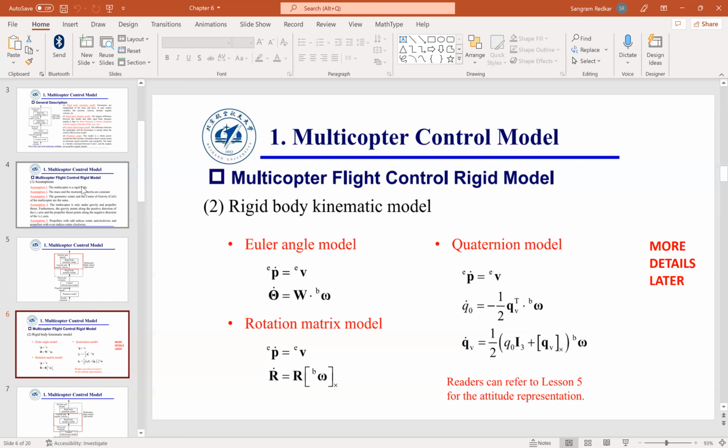This is super important. As soon as this UAV rotates, its rate will no longer be equal to the roll rate, pitch rate, and yaw rate. Do you understand that? Because now this coordinate frame, so initially it was like this, it yawed. And when it yawed, maybe yaw rate is same, but roll rate and pitch rate is no longer equal to the pitch rate and roll rate in Earth center, Earth fixed coordinate frame. Everyone understood this?